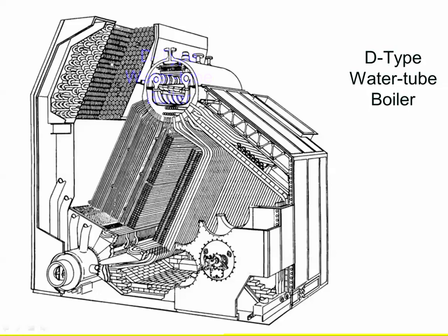The reason for this is the superheater. Now, a lot of the old Navy books will talk about the screen tubes protecting the superheater, and that thought process can get you in trouble. It's really a misnomer. These screen tubes were put in for another purpose. They are actually there to help regulate superheated steam temperature through changes in load, like going from low load to a high load. I always want my superheat to be 940 degrees, not 910, not 950, 940.